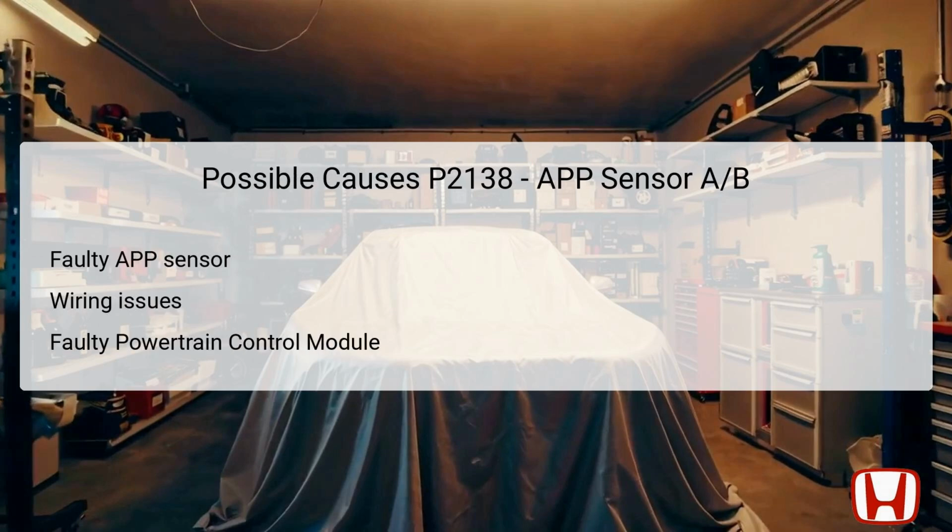The possible causes of DTC P2138 often include a faulty APP sensor, which can fail due to internal defects or physical damage, resulting in incorrect voltage readings. Wiring issues might also contribute, where the wiring harness could be shorted or have poor connections, leading to communication failures between the APP sensors and the PCM.